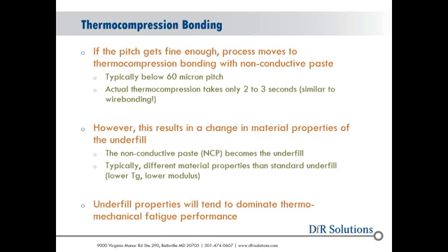So let's talk about those 7 drivers, and some of them right now. One of them is electromigration, again, one of the highlights from Intel's perspective. And when we're talking about similar dimensions, copper pillar is definitely much better, okay? It outperforms solder bump by as much as 3x, right? And there are a number of reasons for that. Higher electrical conductivity is one, higher thermal conductivity is another.